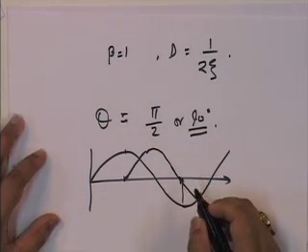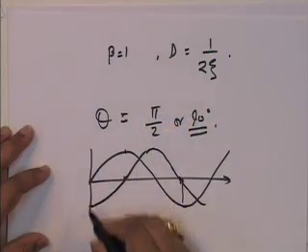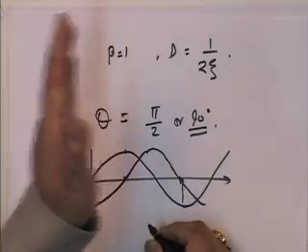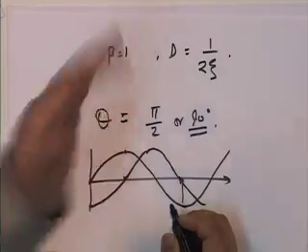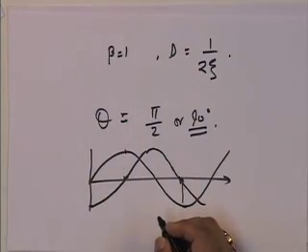Okay. So, when beta is extremely low, the response is in phase with the load because it is static. When beta is 1, which is resonance, dynamic amplification is 1 upon 2 xi. In other words, the response is extremely large and it is 90 degrees out of phase. So, it's almost like, if sine omega bar t is the loading, then minus cosine omega bar t is my response.